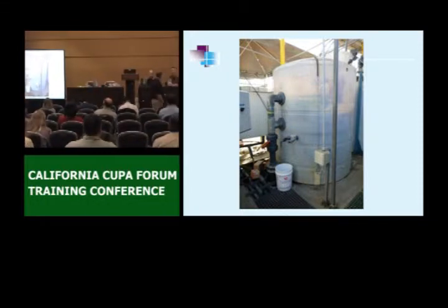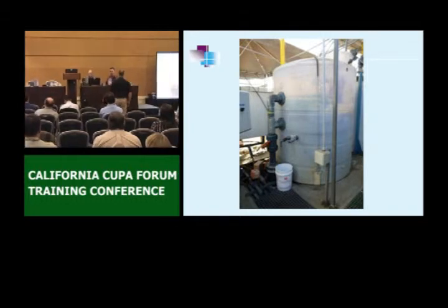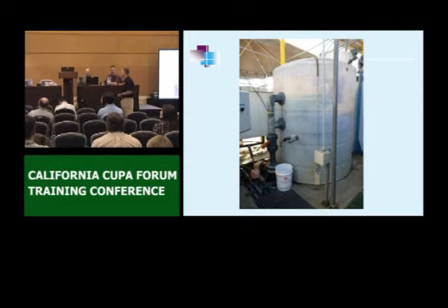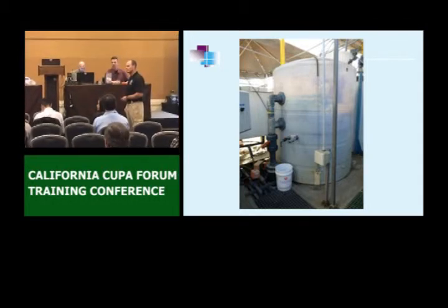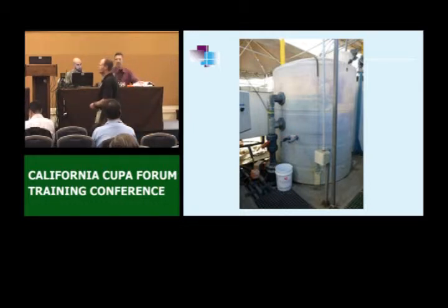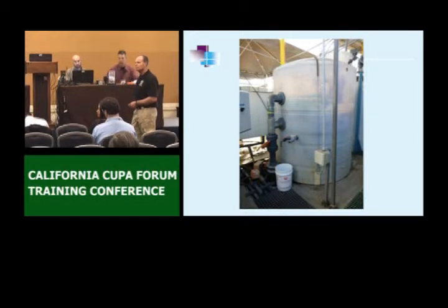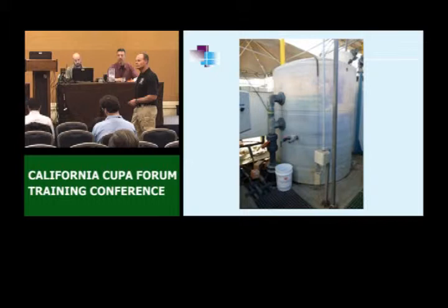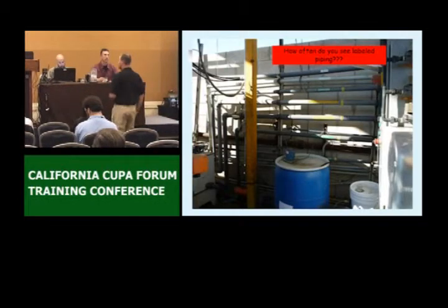Can I ask a question? Are you applying the CalARP requirements to PE assessments for hazardous waste tank systems? A CalARP facility, a lot of the refineries where they have pipe runs, a lot of huge tanks. Right. No, that's a good approach. The CalARP approach is good, and they look at worst case scenarios, but we're just sticking within the Chapter 10, Article 15 hazardous waste tank system standard. The guidance document applies to any type of tank, any type of piping, any type of pipe runs, if it's a CalARP chemical subject to CalARP or RMP, whether it's hazmat or waste. It doesn't care. It looks at seismic effects on tanks and piping. We just don't have any authority to do that under this program, so we use that guidance document. Yeah, that's a good document. Thanks.